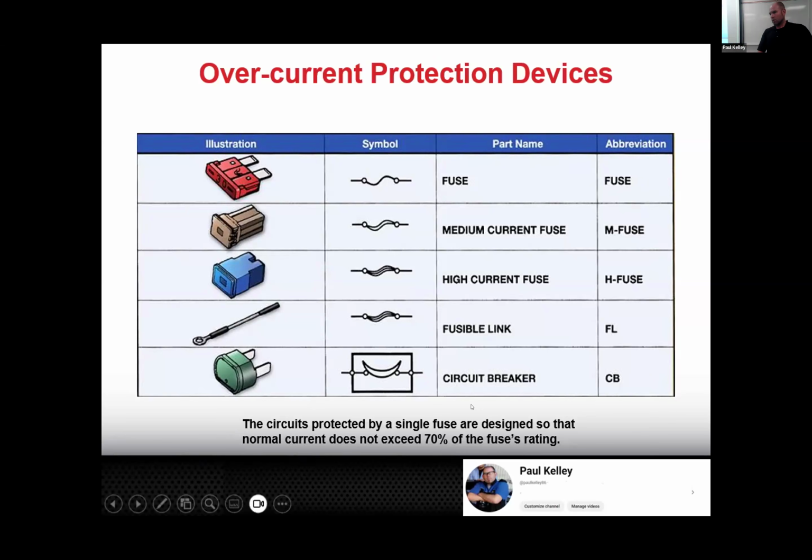Do they always have that clip on it? Not necessarily, but this is actually pretty accurate. This is probably connected to the battery, and then it's got this little spot where the big wire is spliced to the small fusible link wire, and another one. So they'll usually have some sort of connection looking thing, and then in the middle, this will be like just a little bit of a different looking type of insulation, more rubbery, thicker, kind of weird.